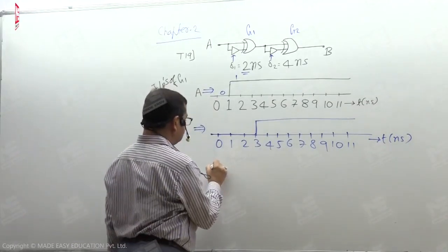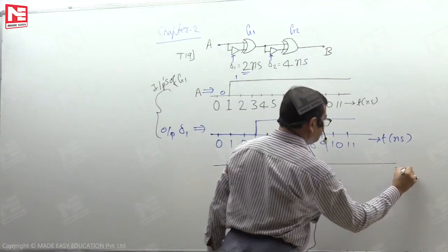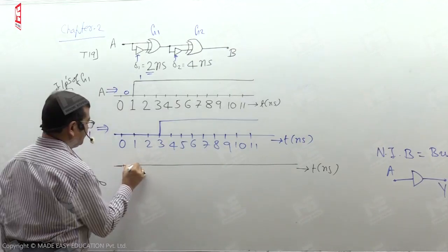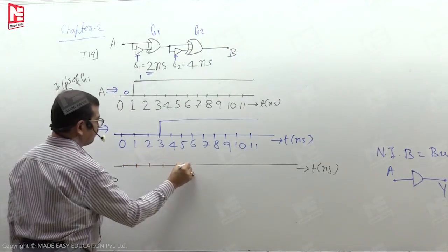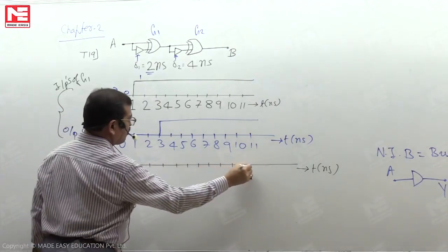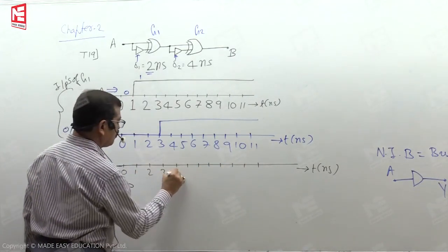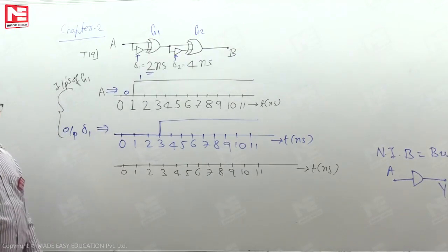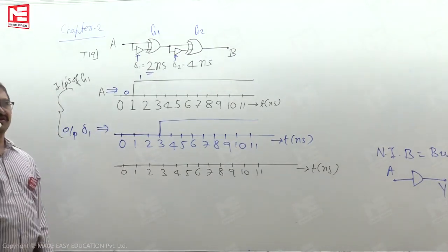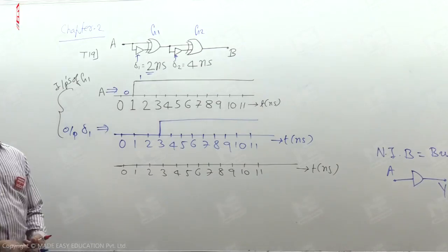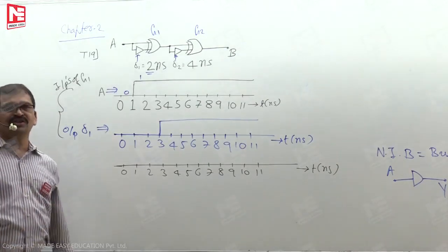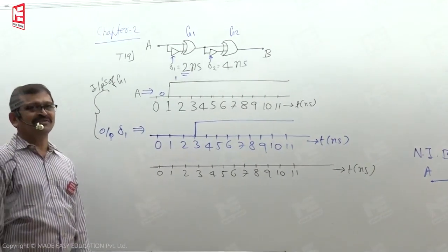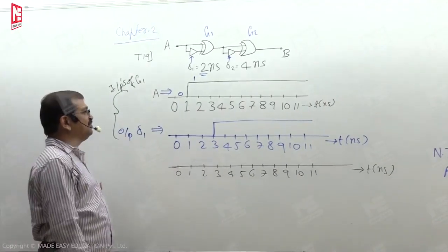Knowing these inputs, we are looking now quickly. So knowing this, we are quickly giving the waveform of the gate G1. So G1 is an exclusive OR gate, XOR gate truth table. We know whenever both the inputs are the same, the XOR result must be 0. Whenever both the inputs are not the same, the XOR result must be 1.